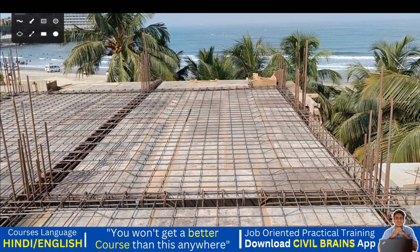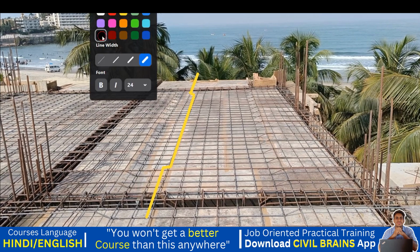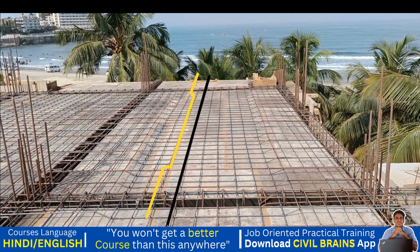And one more thing I want to make clear. Right now whatever slab we are seeing, it is all a one-way slab. Suppose if it was a two-way slab, then what would have happened? Even from here also we would have got a crank bar. Your bar would have come here, it would have got cranked, it would have come here. Similarly, the next bar would have been your straight bar, and after that again the next bar would have been your crank bar. Got it? So if you do the crank on all four sides, then it would be your two-way slab. Right now it is only a one-way slab because we are cranking only in this direction and this direction, whereas in this direction your bar is going straight, it is not cranked, so it is a one-way slab.